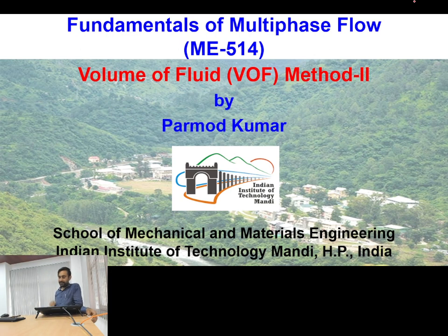So already I explained to you that in case of volume of fluid we treat our two phases using the one fluid formulation, and at the interface we introduce a surface tension force. And in addition we solve one more equation for volume fraction in order to differentiate the two fluids from each other.